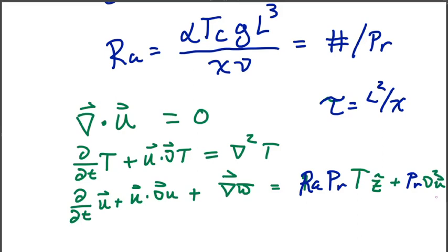We can see those clues in the fact that the non-dimensional numbers remaining in the momentum equation are on the buoyancy term, and they are on the viscous diffusion term. But when we look at the temperature equation, the diffusion term and the advection term do not have non-dimensional numbers. That can clue us in, examining visually a set of equations, that the system's been non-dimensionalized based on the diffusion time of the temperature system.